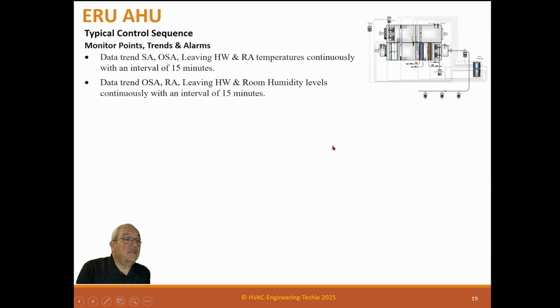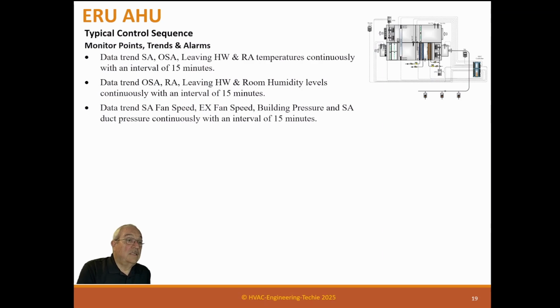Data trend the outside air, return air, leaving hot water, room humidity levels continuously with an interval of 15 minutes. And these are diagnostic in nature. Data trend the supply air fan speed, exhaust fan speed, building pressure, supply air duct pressure continuously within an interval of 15 minutes. And these are diagnostic again.